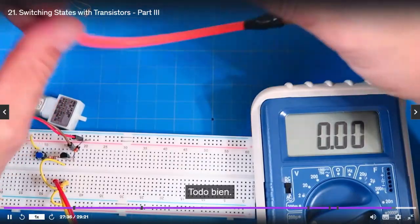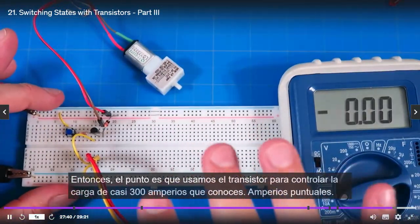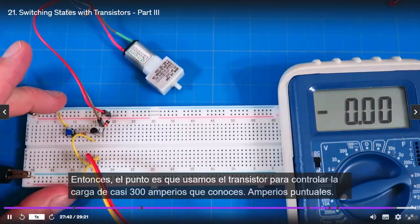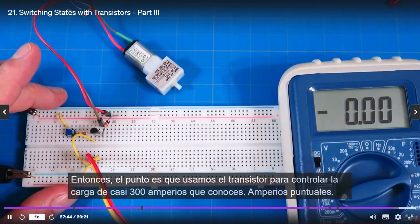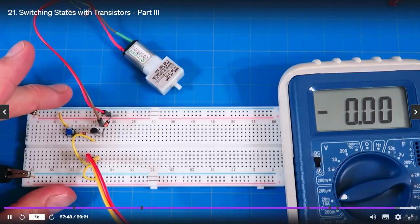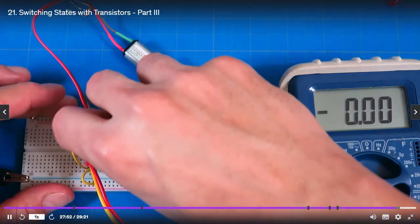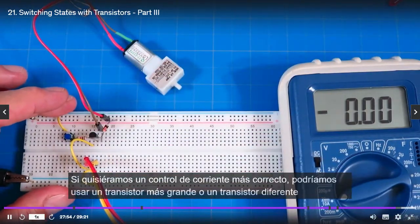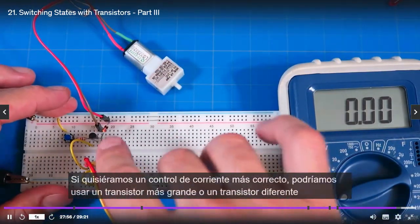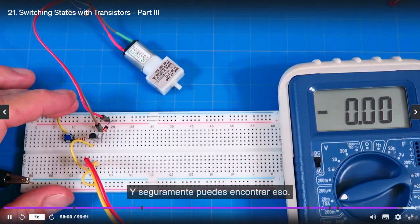All right. So there's a little mechatronic system. The whole point is we use the transistor to control a load of almost 300 milliamps, 0.3 amps. That's a lot of current, right? All with our transistor. Now, if we wanted more current control, we could use a bigger transistor, a different transistor that's designed for amps, and surely you can find that.